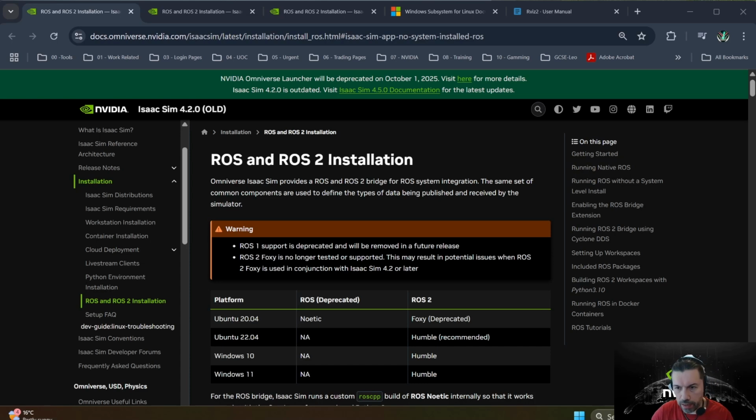So we are going to learn how to stream the Lidar sensor data from Isaac Sim to ROS2. ROS2 is a middleware framework for building robot applications, enabling communication between sensors, logic, all that in real time. Isaac Sim has built-in ROS2 support, and you can run the Isaac Sim ROS2 bridge extension to do so. We will see it in a bit.